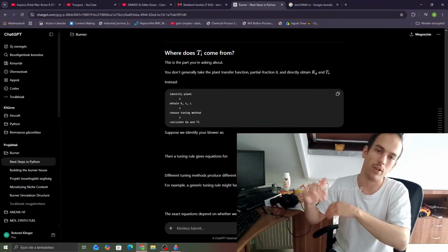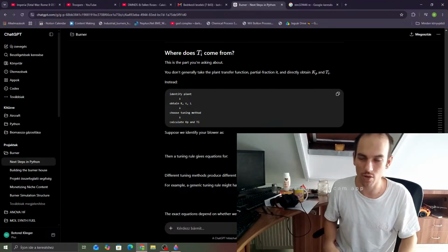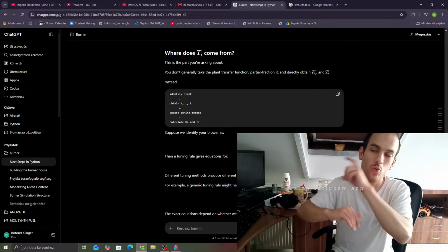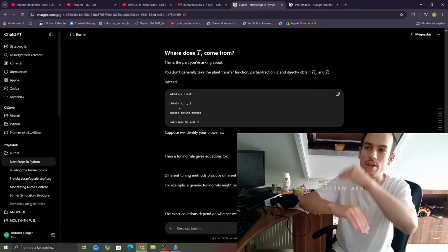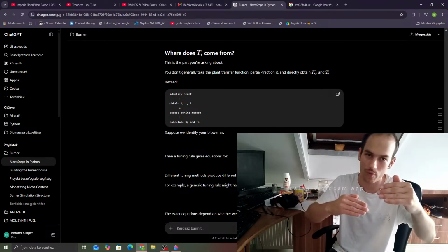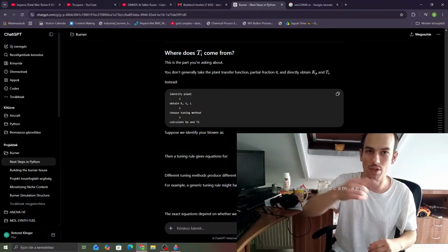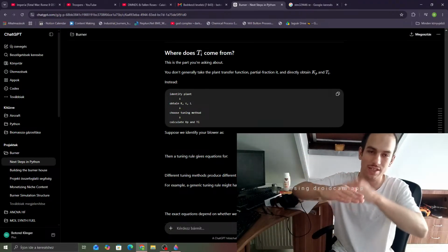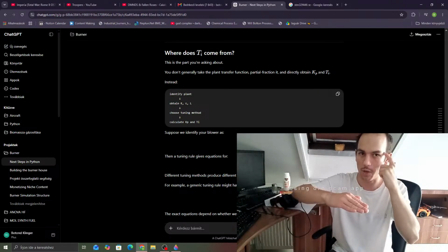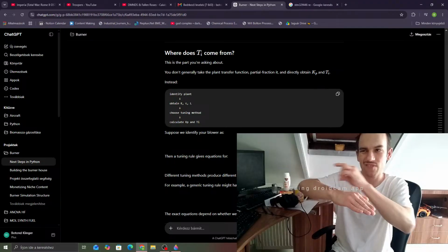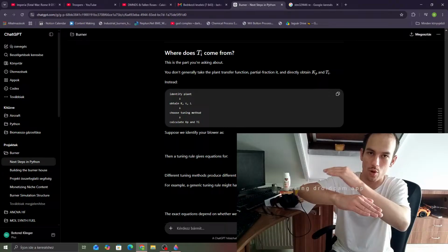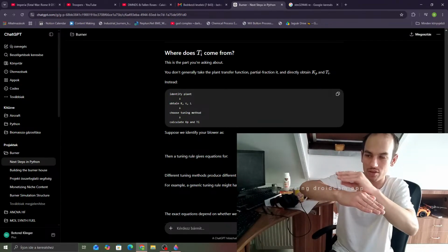Let's say you have a volumetric flow of 10 liters per second, you add the proportional gain, and it overshoots by, say, 0.5 liter, then undershoots, overshoots, undershoots, because it increases and decreases the PWM, but it never reaches the desired volumetric flow. Therefore the integral, which has a memory, sums up +5, -5, and proportional to the memory it is going to decrease or increase.